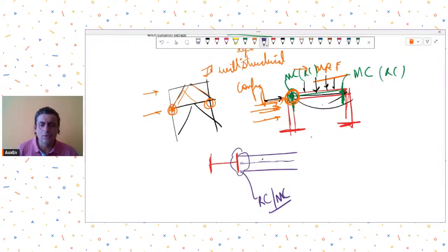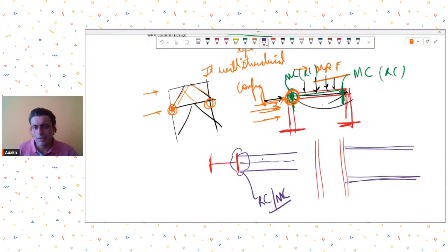It is easier to develop a moment connection over here because the arrangement allows you to have a rigid connection made. I can develop rigid connections over here by providing end plates, which is called the extended end plate connection, or there are other options also, by providing some T junctions or whatever.